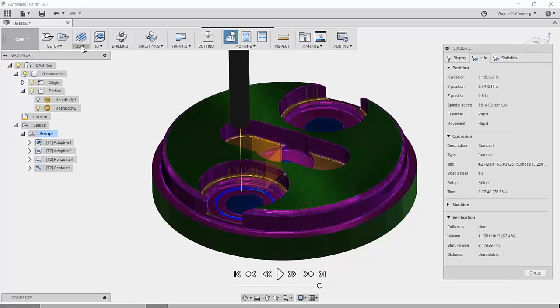Whenever you're going to get a file, you always want to get things as close as you can to the native. Now, us being able to machine an STL is a pretty significant thing because of the way an STL works. Wayne has been referring to the facets, and that's really how you have to look at an STL. Think of it if you wanted to machine a diamond. A diamond is made up of a bunch of facets. Diamonds are never round. They always have facets on them. And the fancier diamonds have more facets.